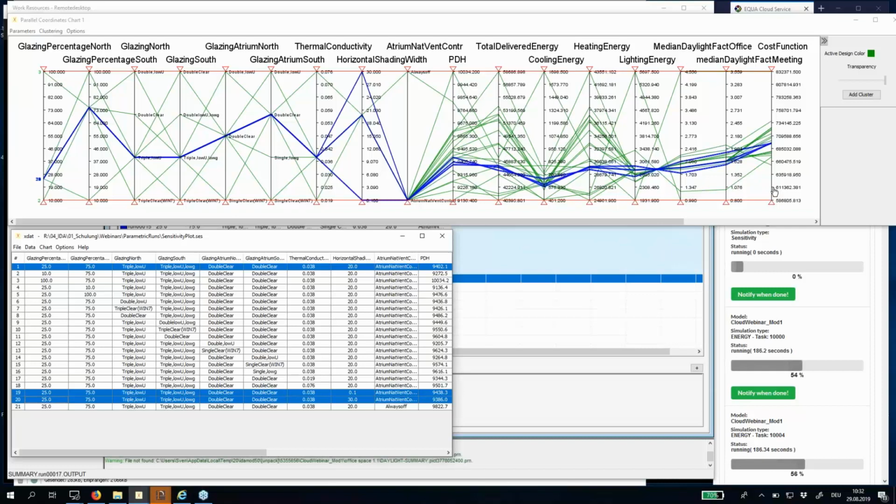So actually this is the sensitivity analysis. We could decide to throw this horizontal screen width variation out of our future studies because it's not very sensitive, just to save some calculation time for the continuation of the optimization study. But we keep all these input values, and we want to run a Monte Carlo simulation next.